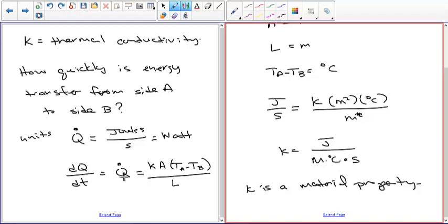In this case, what we're going to do practically speaking, and I guess we have to do it this Wednesday or next Wednesday, is this: if you're calculating the amount of heat transferred from your house or any building, it basically comes down to this equation. They always tell you to turn the thermostat down to save energy. Well, if this temperature difference is smaller, you're going to have less energy transfer. They tell you to put more insulation into your walls. That increases this, and that lowers the amount of energy transfer.